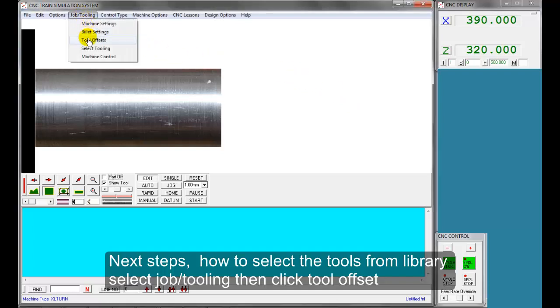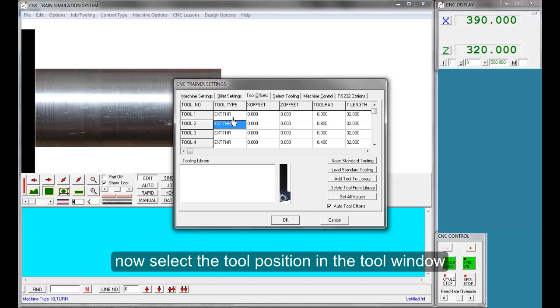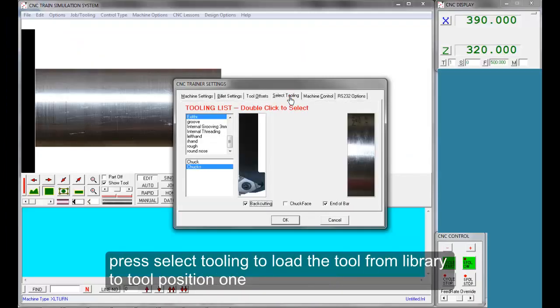Select Job, Tooling. Then click Tool Offset. The Tool Offset page displays the tool library. Step 1. Delete the existing tools in the library. Now select the tool position in the tool window. Now the tool 1 is selected. Also verify the tool position in the machine turret. Now press Select Tooling to load the tool from library to tool position 1.